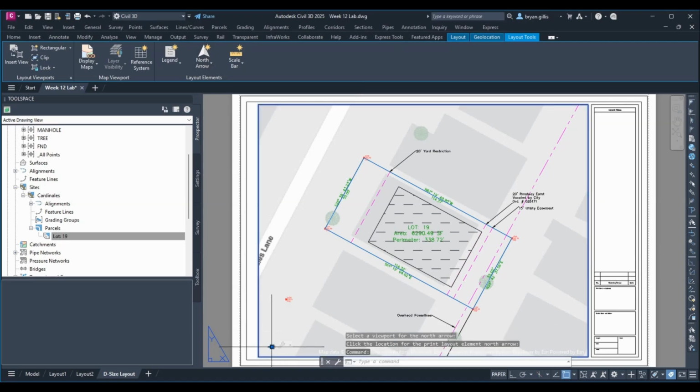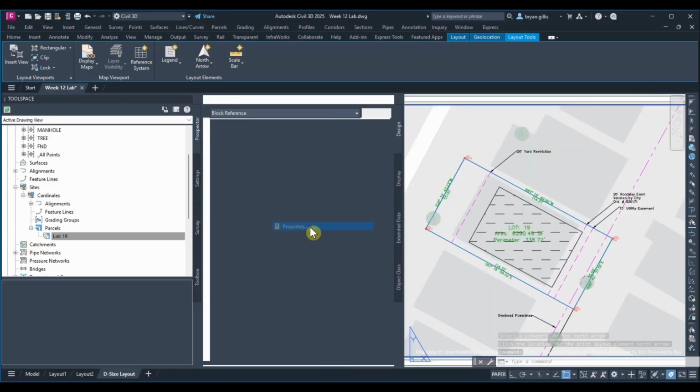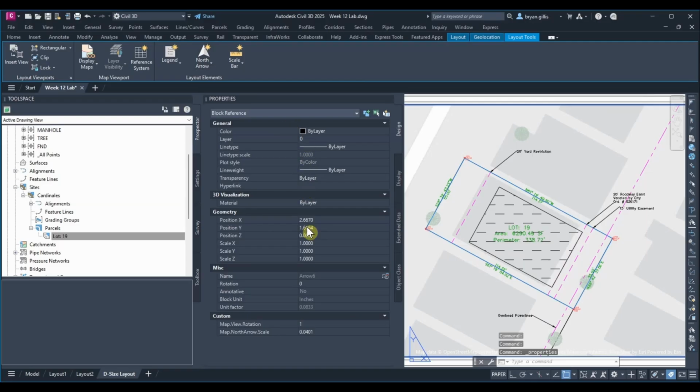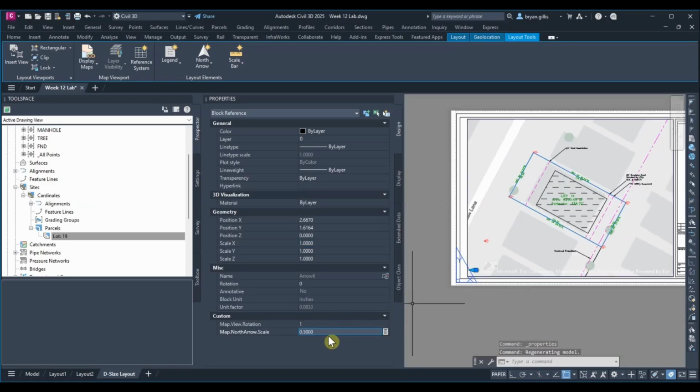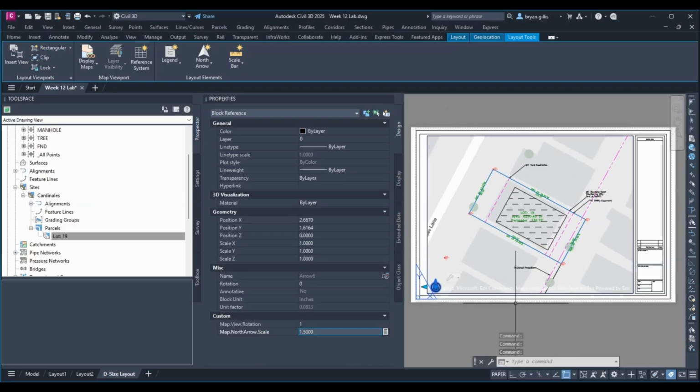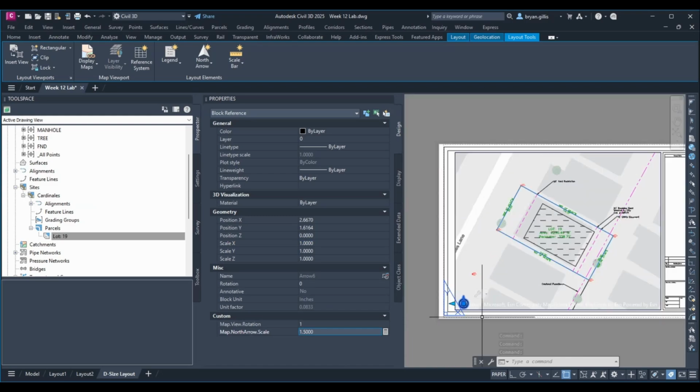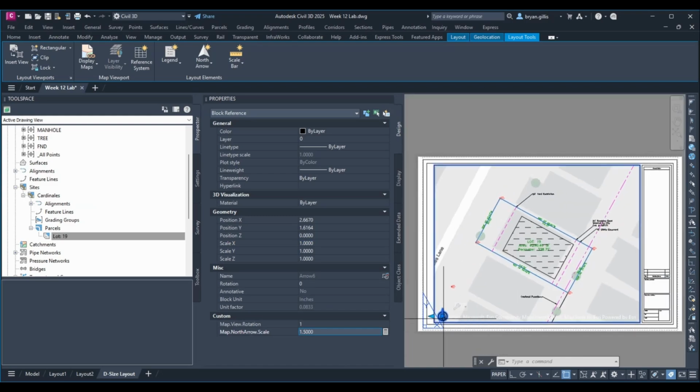You see this tiny little black dot, that is the north arrow. So we're going to have to adjust its properties as well, so that it's not microscopic. So let's go ahead and change the X and Y scale factors. Actually, we can just change the whole north arrow scale factor from 0.1. Let's say 0.5, still tiny. 5 is gigantic. It's the USS Enterprise coming through now. 1.5. That's pretty clean. Again, you don't need a giant north arrow that's going to take over your entire drawing. It can be subtle.